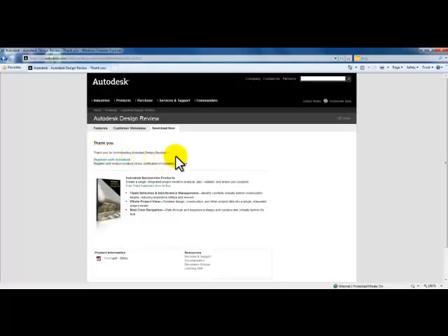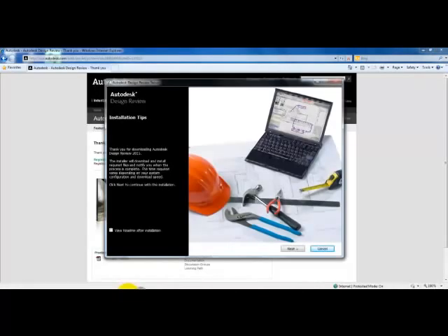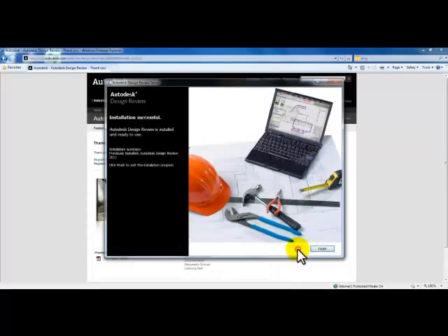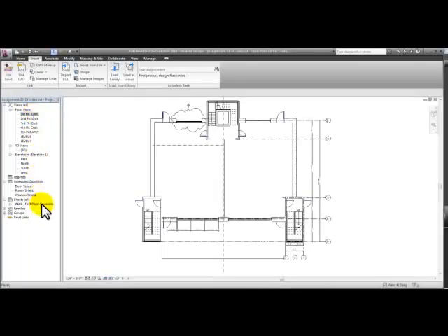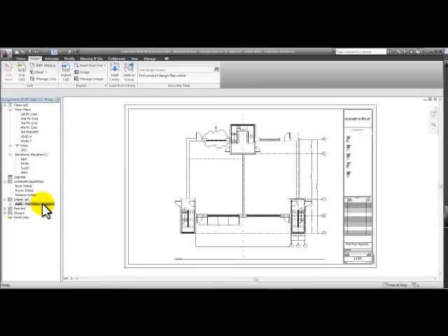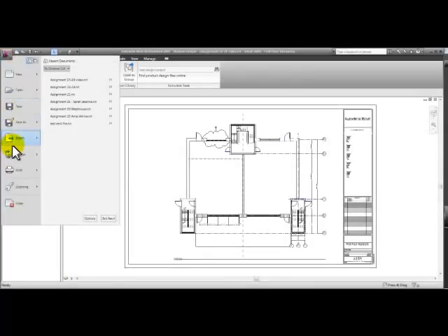They can open the drawing using the design reviewer, mark up the drawing, and then send it back to you. You can then link it to your Revit file and see the markups. I'm downloading the Autodesk Design Review, and in the Revit file, make the view current that you'd like to export, and then go to Export and DWF.